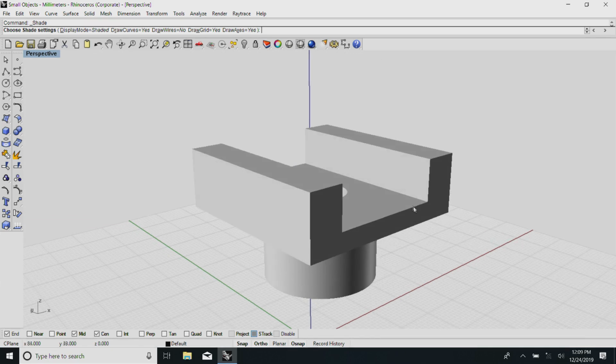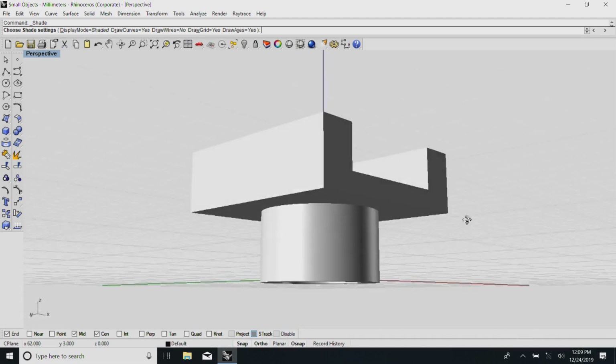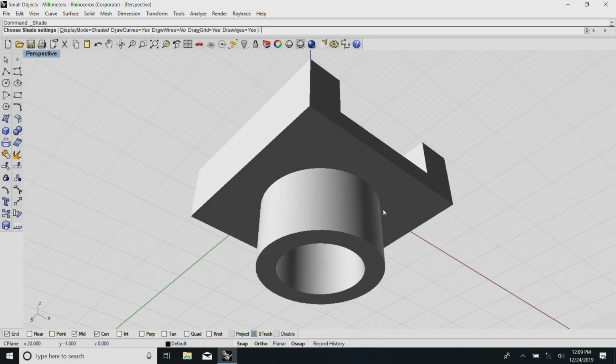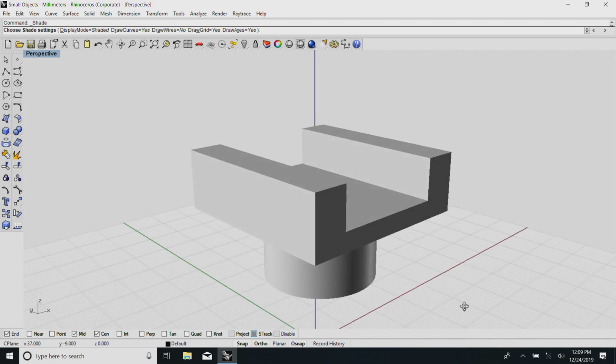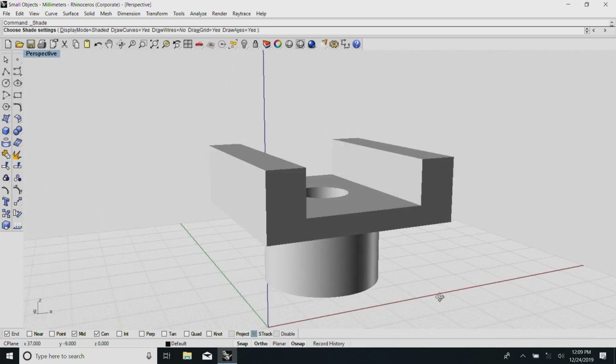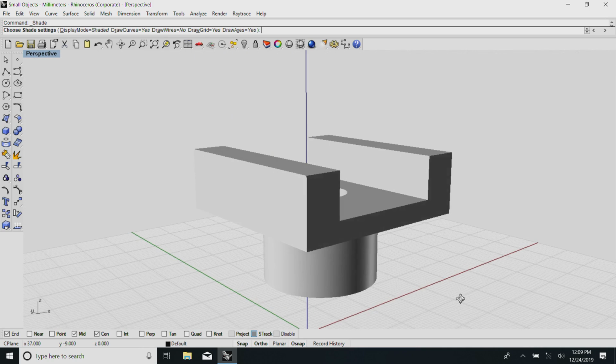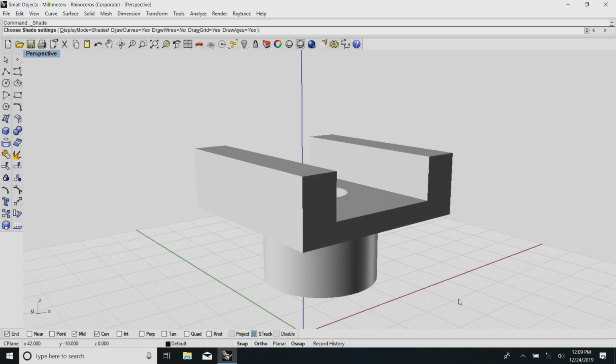And now to make the extrusion, I just need all these 4 things and then take it along here, and then to make this pipe I need to have the internal and external dimensions, and eventually when we join them together we will have the same job which has come here. Yeah, I hope you are with me at this point. This has been created in one way. There are any number of ways in which it can be created. Now, what we generally choose depends on the thing which you are familiar with.